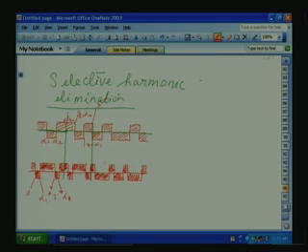At the same time, we have the half wave symmetry; we can see here, this negative half is equal to the positive half. Now, we have to decide what should be the width of alpha 1, alpha 2, or the angle at which alpha 1, alpha 2 should be introduced such that the pole voltage switches between plus VDC by 2 and minus VDC by 2.